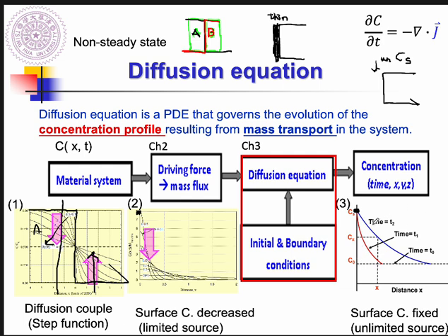So as time increases, you can check at a specific time point or location. It was here, but with time the concentration of diffusing agent increases as well. But no matter whether it is time T1 or T2, the surface concentration is always fixed at C0, Cs. Because we provide an unlimited diffusion source on top of it.